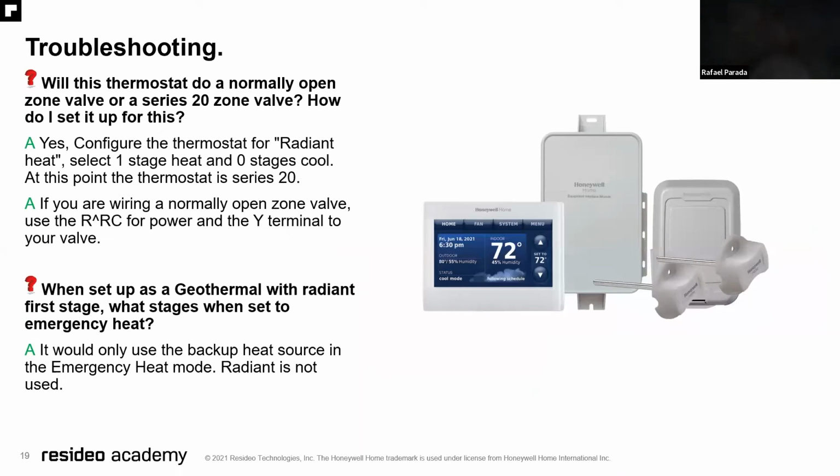Really common question, especially from contractors. RedLINK devices, are they compatible with normally open zone valves or Series 20 zone valves when talking about the hot water system? The answer is yes. This is going to be only for Vision Pro, the 8000 family, and the Prestige, the 9000 family. So the Focus Pro 5000 and 6000 are not compatible with this application.